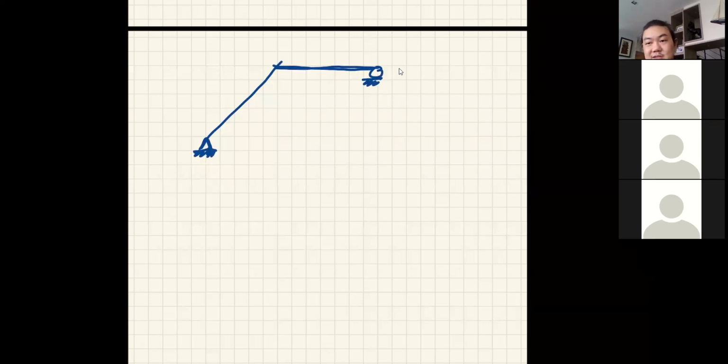Now I used to say solve this by using the slope deflection equation. That means you're going to have to consider the sideways problem, right? And now how many unknowns are you going to have? This is a very rare occasion where the displacement method becomes more difficult than the typical method, because it's a determinate structure.